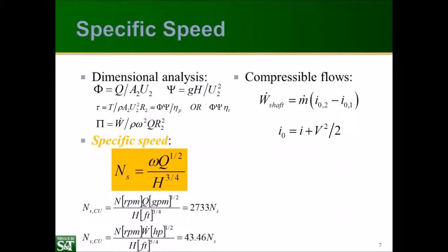Now, since the density can change, we need to have a little bit of a change in our dimensional analysis. We assume we have a perfect gas. A perfect gas is an ideal gas, which follows the ideal gas law, with constant specific heats. So the specific heat doesn't change. Now, most of the time, when we scale turbomachines, we use full-scale prototypes with the prototypic fluid. So we can eliminate the geometry of the rotor, the diameter, the radius, etc., and some of the fluid properties, like the ideal gas constant or the specific heat ratio, from our scaling analysis.